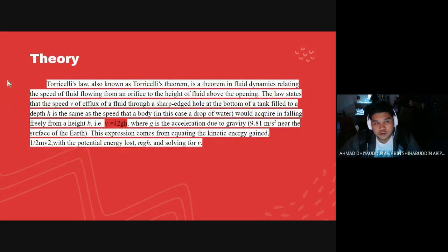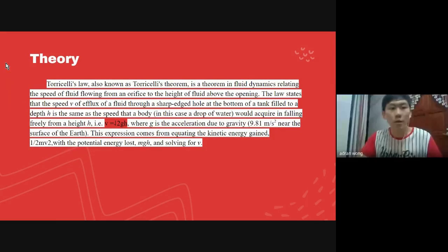Next is the theory part. Torricelli's law, also known as Torricelli's theorem, is a theorem in fluid dynamics relating the speed of fluid flowing from an orifice to the height of fluid above the opening. The law states that the speed v of efflux of a fluid through a sharp-edged hole at the bottom of a tank filled to a depth h is the same as the speed that a body, in this case a drop of water, would acquire in falling freely from a height.